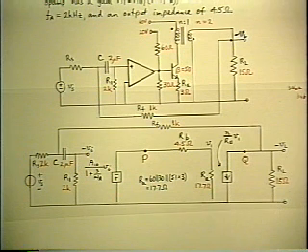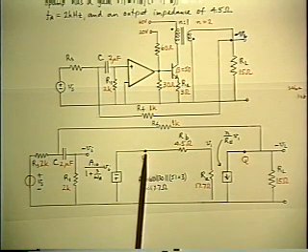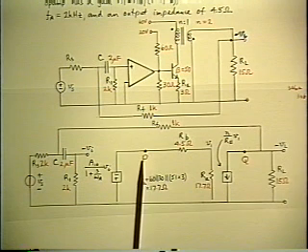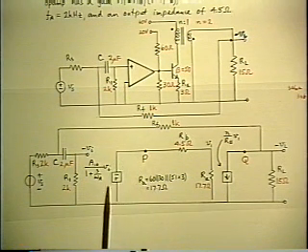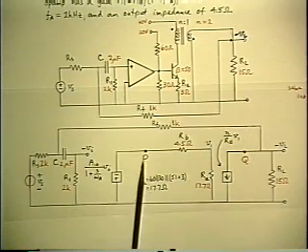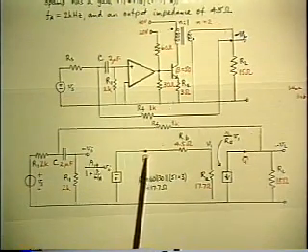Okay, now we have a linearized model. The loop is closed. Now we want to choose a suitable injection point. Already we take into account the fact we're not going to break it. We're going to use the equivalent technique of injecting the test signal. So where can we inject the test signal? And there are several possibilities. Point P satisfies the conditions for voltage injection because it's right after an ideal voltage generator. So we won't upset the loading if we inject the test signal at point P.